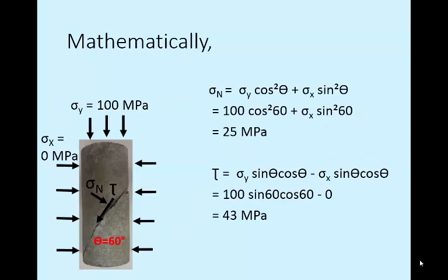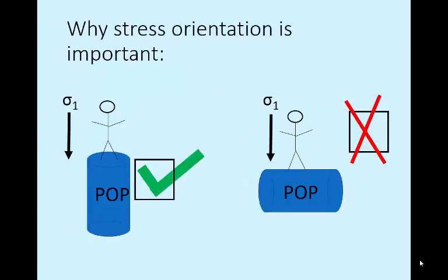Instead of using the Mohr circle, you can just memorize the stress equations for shear and normal stresses as shown here. These are derived in the appendix at the end of the presentation, and I encourage you to stop the video at that time and convince yourself that these equations really work. The key to using these equations is that you have to make sure the angle theta is in the configuration for the plane as determined from the derivation of the equation. From carefully drawing the Mohr circle and then confirming the calculation here, you should never get a problem wrong.